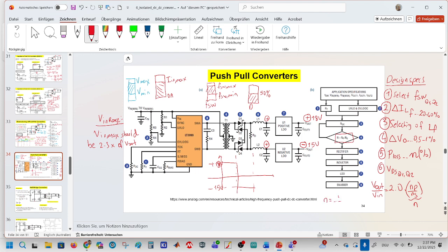If you use a high range of turns ratio, let's say 5 to 10, then the difference between input and output current ratings will be very high, and the reflection of the secondary side to the primary, especially in the previous converters, we had seen that the maximum drain source voltage on the switches is affected by the secondary side.